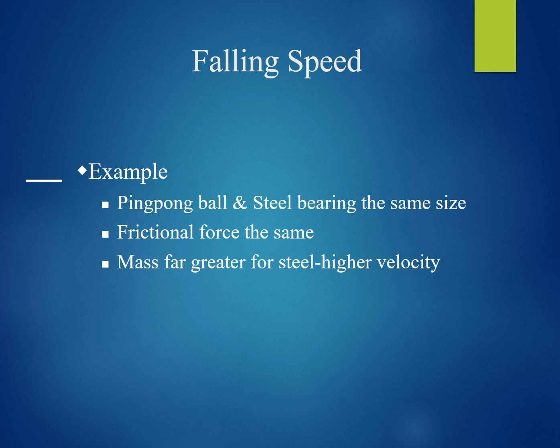The settling velocity or falling speed of a particulate is dependent on the mass, size, and shape of the particle. Larger particles will settle out faster, as well as heavy or dense particles. Lighter particles, or those with a fibrous shape, will tend to settle slowly and can be re-entrained in the air by the air currents themselves or movement around them.